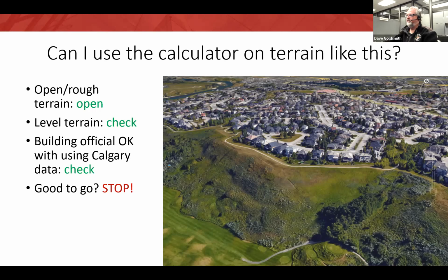The reason was probably excessive deflections due to wind speed up over hills and escarpments, affecting the very large picture windows overlooking the scenic valley and causing wear and tear on the sealants that resulted in leakage.